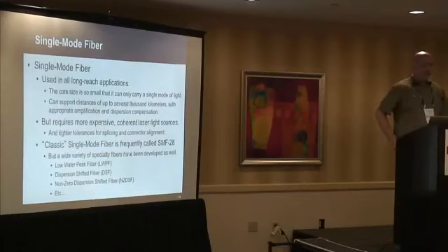Single mode fiber is what you use in any type of long reach application. So the core is small enough that you can only have one mode of light inside it, and that lets you get several thousand kilometers without completely regenerating the signal. Obviously, you still have to amplify and do dispersion compensation, things that we'll talk about later, but you can actually get really long distances with single mode. But obviously it's more expensive. You need tighter tolerances, you need lasers that are specifically aimed, things like that.